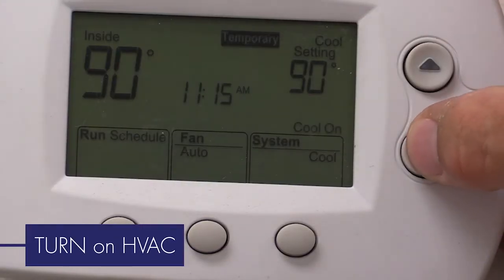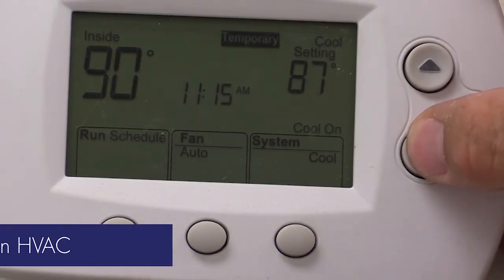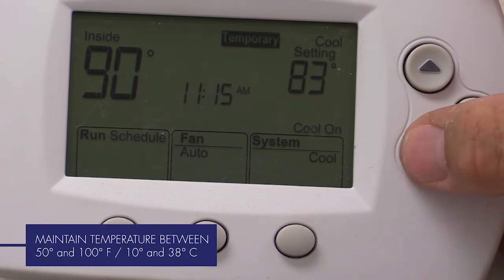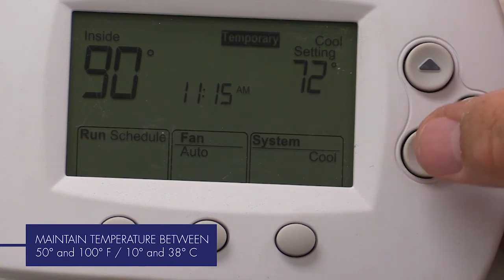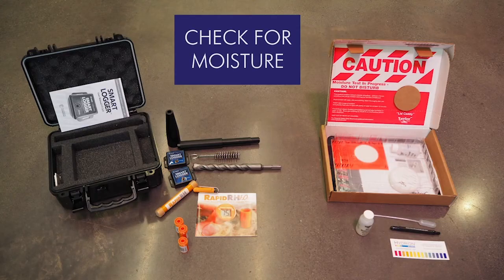Next, turn on the HVAC at least 1 week prior to installing. Room temperature should be maintained between 50 and 100 degrees Fahrenheit or 10 and 38 degrees Celsius for at least 48 hours prior to installation. Next, confirm the substrate is suitable for use with Engage Genesis and perform the appropriate moisture checks.